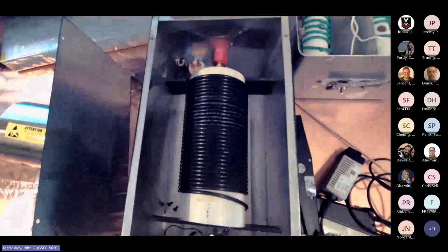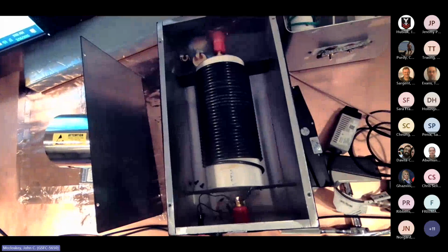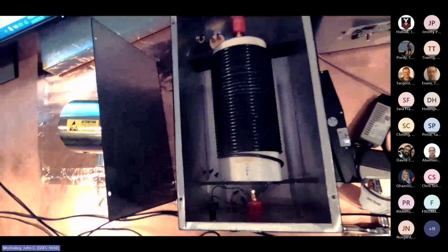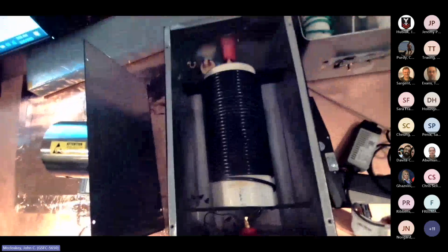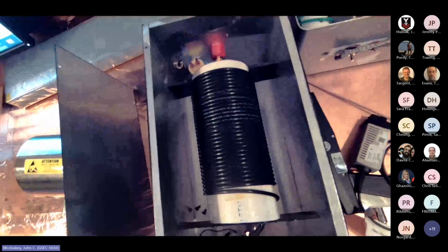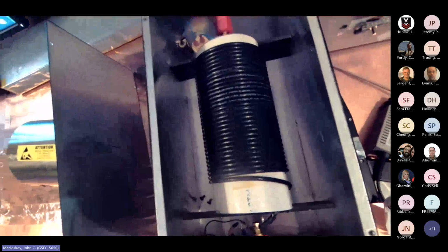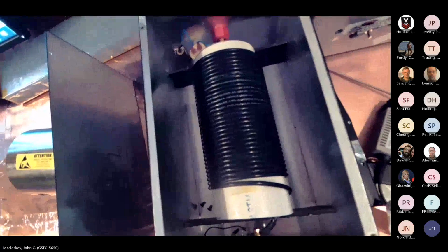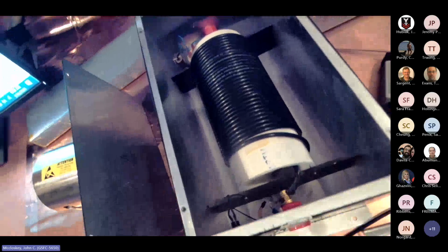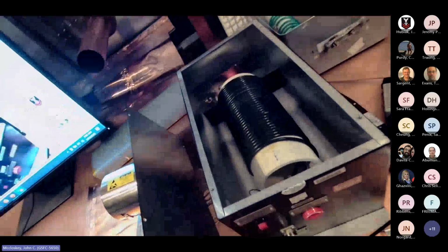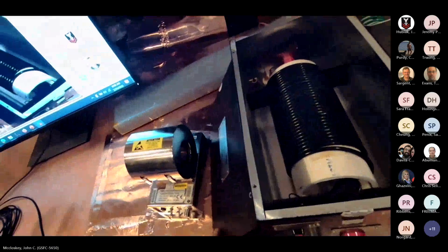And that's, of course, the main portion of this LISN. LISNs are generally identified by the inductor value. There are some capacitors and other components in here, according to the schematic in the Mil standard, but the business end of this thing is the inductor. And I mentioned this last week: this is a line impedance simulation network.